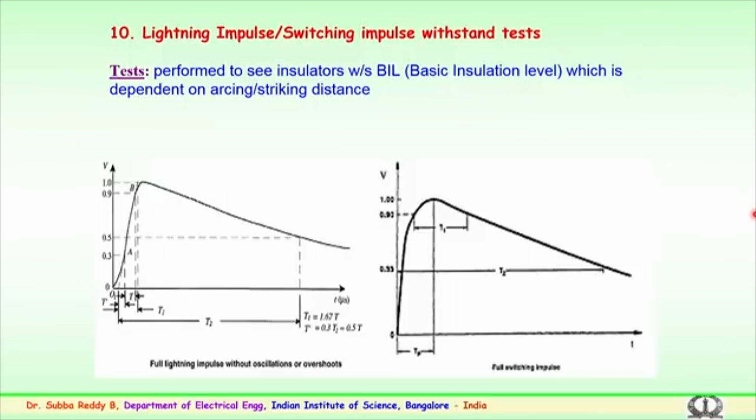So, we have discussed lightning impulse and switching impulse. Again, this is one of the important type tests which are carried out to see that the insulators perform, particularly withstand the basic insulation level for which they are designed, and it is dependent on arcing or striking distances.